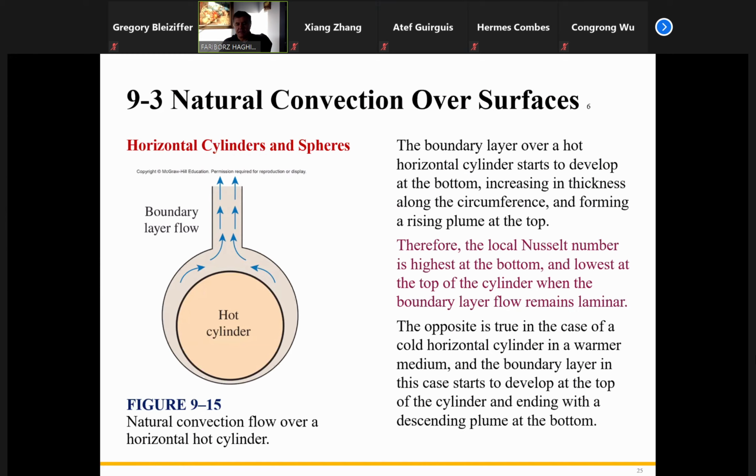Now, the same thing happens again for the next geometry. We're talking about cylindrical coordinates. Again, the temperature is hot. The cold air closer to the cylinder gets warmer, warmer, warmer as it goes up, and therefore the thickness of the boundary layer is higher, thicker, up here, and thinner down here. Down here, they are approaching. Therefore, this is the boundary layer to scale.